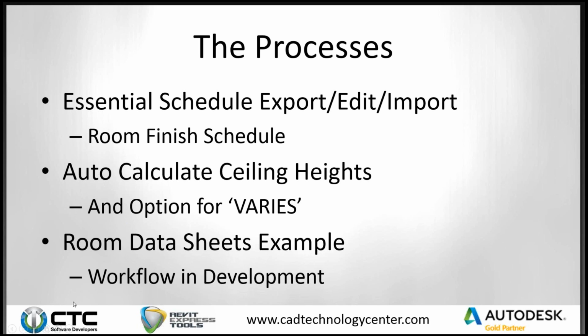This is one where I've got furniture placed into a room, and I could do this for casework, and I could do this for lighting fixtures, and I could even do this for the room materials if I wanted to. But what I'm going to do is for the furniture specifically. For my rooms, I want to list my room out, so I want to know what the room number is, I want to know what the room name is, and then what I want to do is have a single row of information with columns. The columns are going to be casework in room, furniture in room, lighting fixtures in room, finishes on room surfaces, or something like that, right? So I can just get the essential information about a single room in a single row in a single schedule.